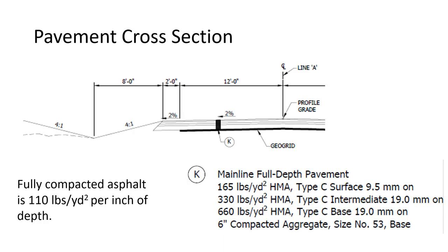The stronger that pavement, the less depth of asphalt you need for that. And this is a flexible one. This is an actual design set of plans. This is showing how we typically call out what our pavements are going to be. And so we've got section K. That's this blacked-in box here that says this is section K. And if you want to know what section K is, you can see there's different layers kind of drawn in there.